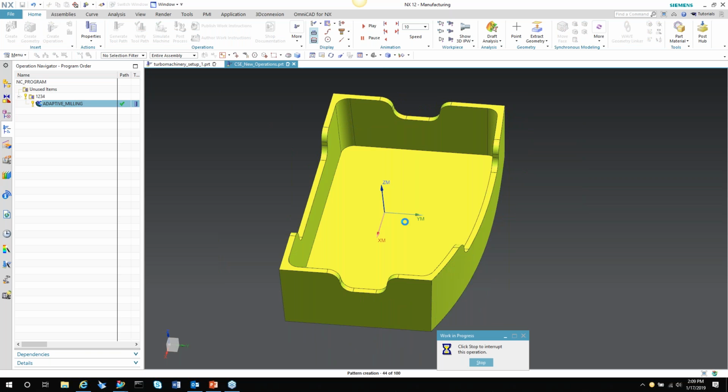creation and its patterns. And one thing that you need to pay attention to is the types of engagements that it has. Traditionally, we have different cut patterns we can select from, but it's a singular event. We have a way to get into the part with our engagement, and then we have our cut pattern that it's going to go throughout the operation with. With this, it goes between 3 different cut styles. It'll do a spiral circle mill into the part.